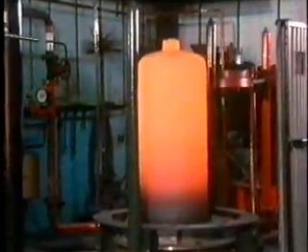These days, many of the carbide inserts have a double coating. The titanium carbide layer gets an additional coating of aluminium oxide. This produces a durable cutting edge, which gives almost twice the metal removal rate you'd get from a single coating.